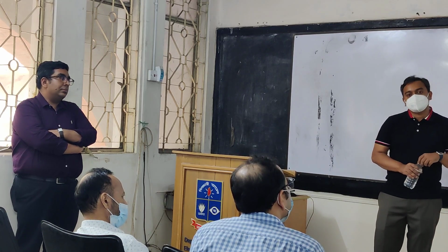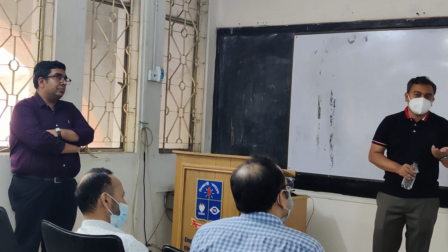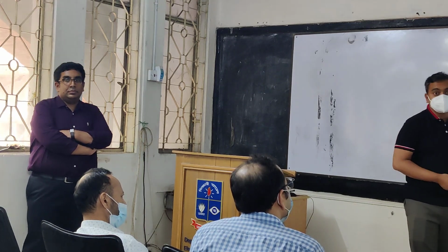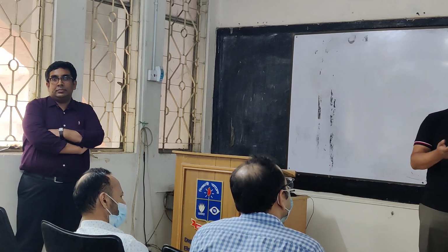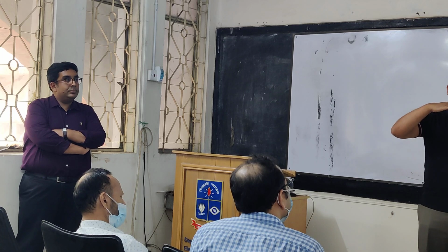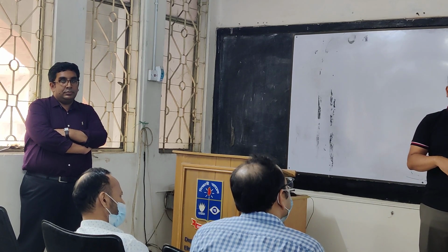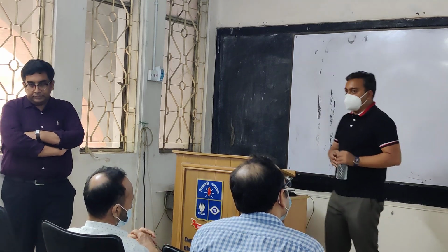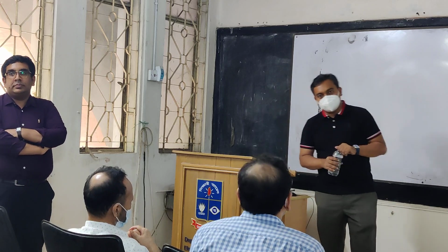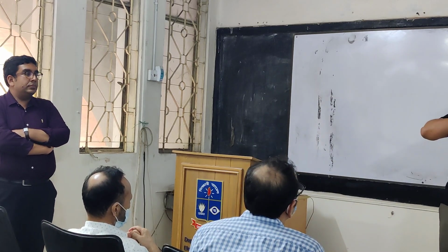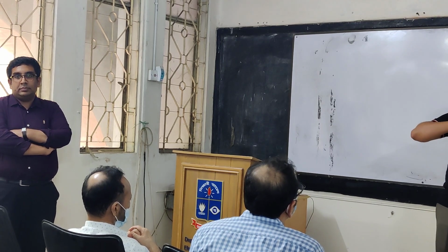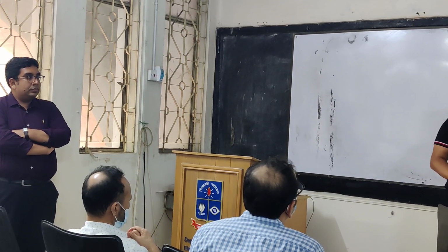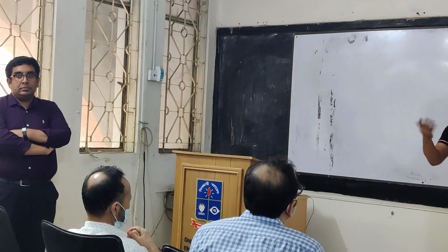Fundamentally, one can say that the switching speed is essentially the same as hafnium dioxide, because switching speed depends on the force that you are applying on a material. And force is Q times E, right? Electric field. And if you have a sheet of charge, what is the electric field? Charge divided by the permittivity. So, in a transistor, whether you have used a high-K hafnium dioxide or ferroelectric hafnium dioxide, the inversion channel charge you have is the same, because that belongs to silicon. So if you have the same charge, you have the same electric field. If you have the same electric field, you can apply the same force on the atom. The atom is the same, which is hafnium dioxide. So therefore, there is no reason for the dynamics to be different.